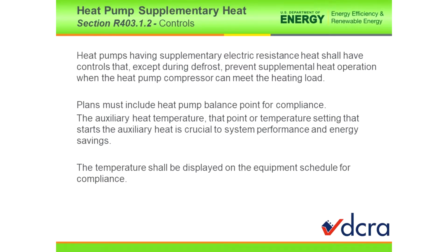So here's how you are in compliance with this particular measure. Now, there's basically two ways, and it may be more, but let's just say two ways that we see most of the time. So one, and the easiest way, if you ask me, is to purchase one of these thermostats that automatically detect the balance point, okay? So far, I only know of one that I've researched, and yes, it works. And that's the Nest thermostat. It has the ability to automatically detect the balance point, okay?